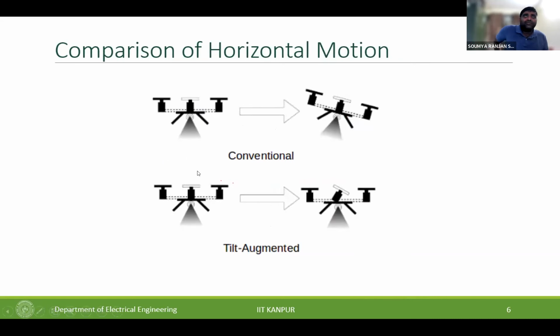Now, one reason I got interested in looking into such designs, where attitude can be decoupled from the position control, was that in conventional or variable pitch quads, the position and attitude states are coupled. If you are trying to survey something and there is a fixed onboard camera facing downwards, then as the vehicle moves, the camera's view tilts.